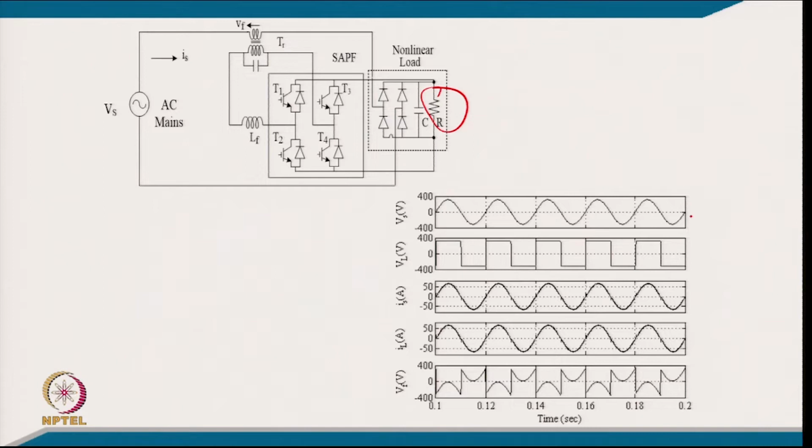So, we have a sinusoidal supply voltage, and we want a DC link voltage of typically 320. Now we are forcing a sine wave current, so the diode has to conduct for 180 degrees. So, the same 320 volt will come to the PCC in square wave form. So, this is the 320 volt square wave, and of course, with proper control we are able to have supply current and load current, which are connected in series, as a sine wave at unity power factor, and now the injected voltage will be the difference of these.